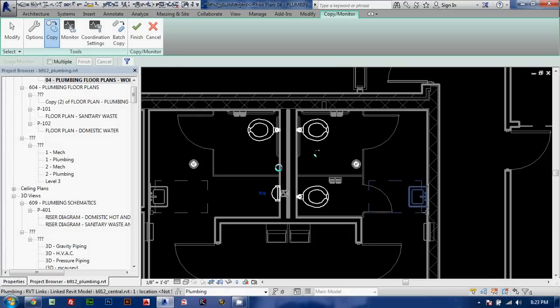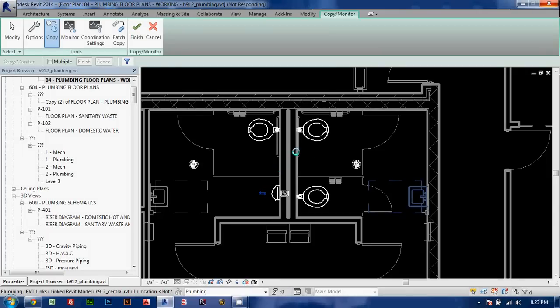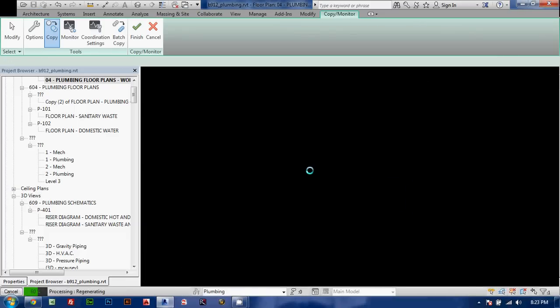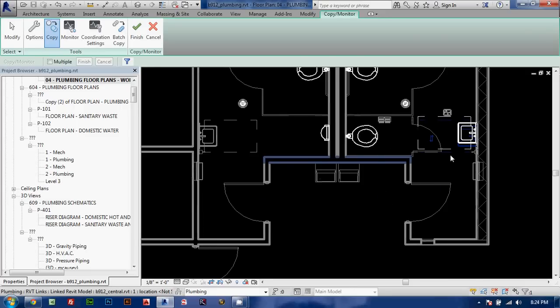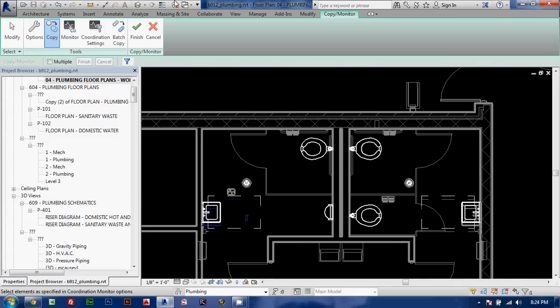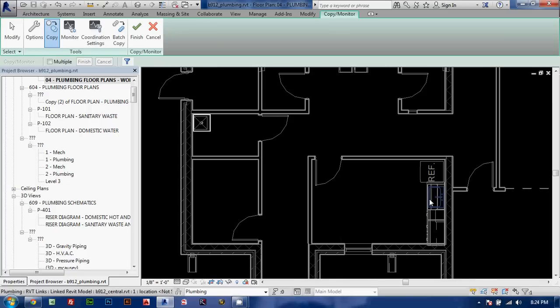It's really important. We had projects before where the plumbing fixtures changed enough that, when you're using slope piping, especially because slope piping in Revit is very finicky, if you were to change the location of one fixture, it might actually force the piping to go non-sloped, which is really annoying.